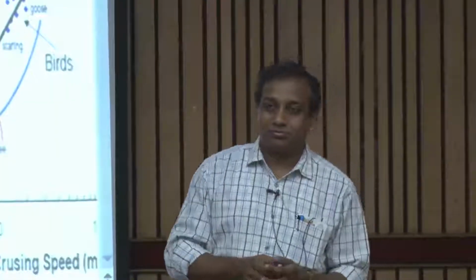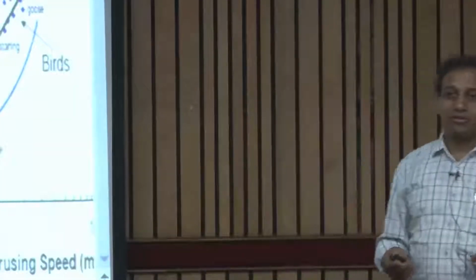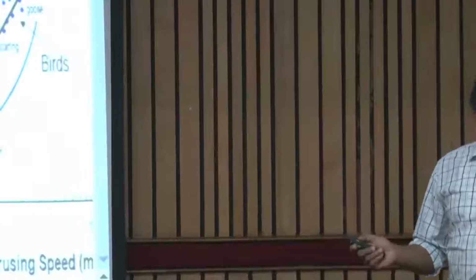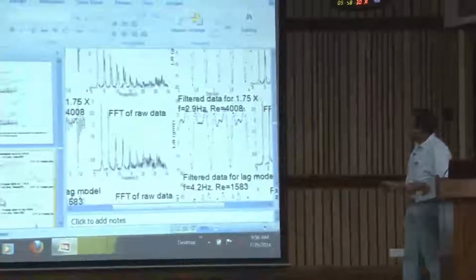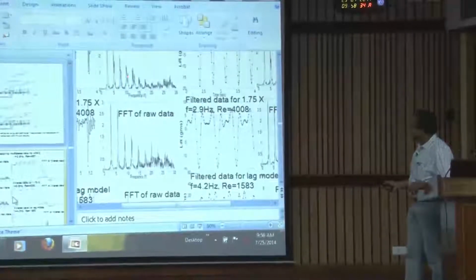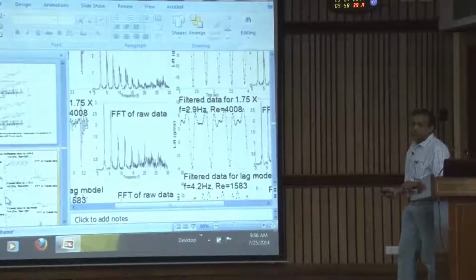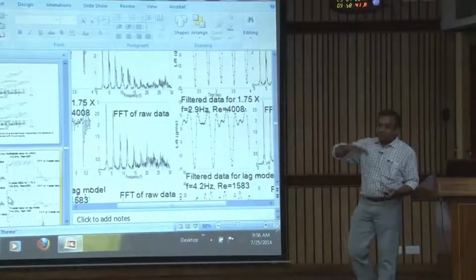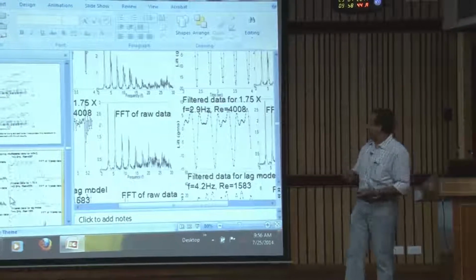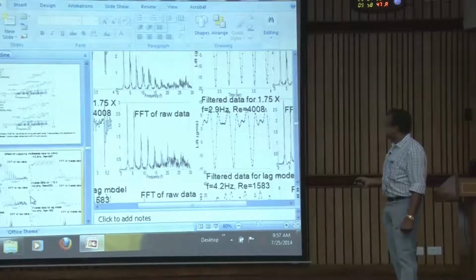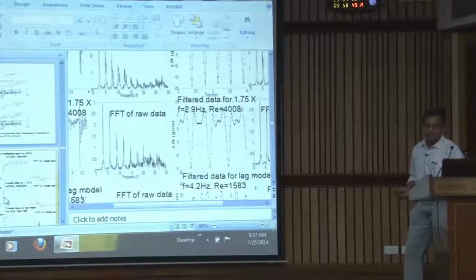Double frequency, no? So it should be just bifurcation rather than this high frequency, no? I don't think they are just double frequency. Yeah, roughly, but I think they're all higher harmonics: 2F, 3F, 4F. So this could be, but I don't think these are higher harmonics. The first four or five you can explain, because over the cycle you can explain from the vortices how it is happening.